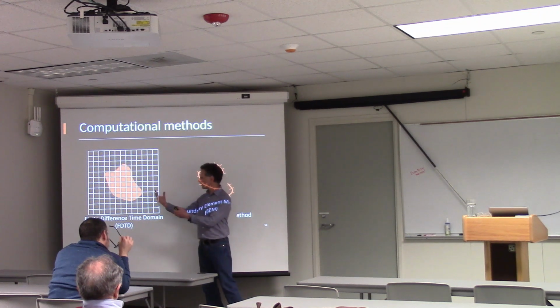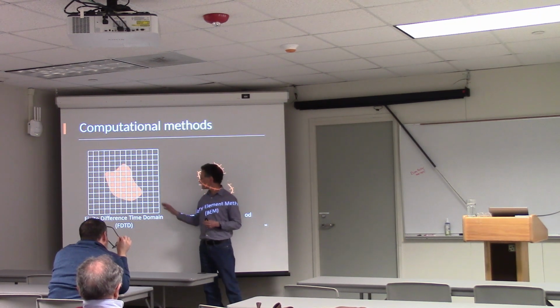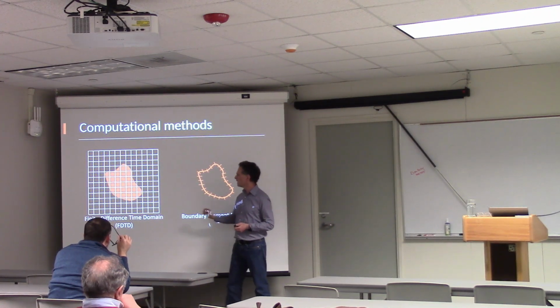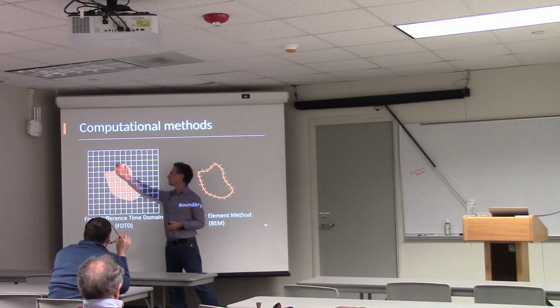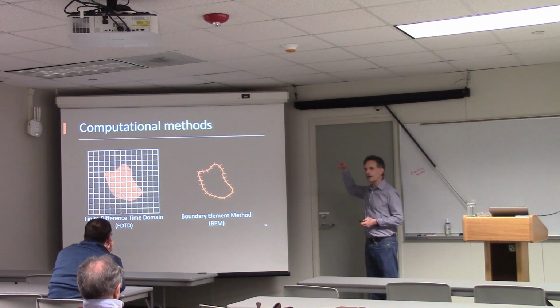In the 3D domain you have x by y by z size. You're going to need 8 to 10 samples per wavelength across the whole domain, and then you have to do enough iterations to get the waves to propagate across the whole domain. So you have an awful lot of factors of the length scale in there, and it doesn't scale to the sizes.